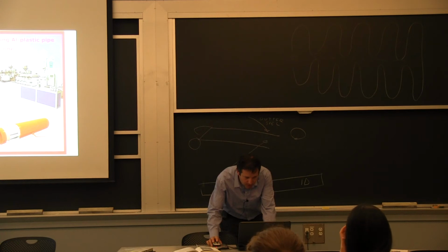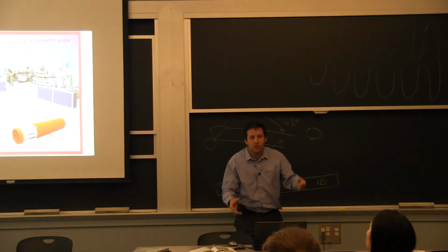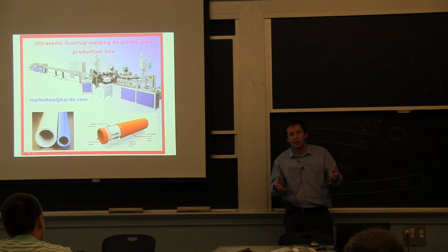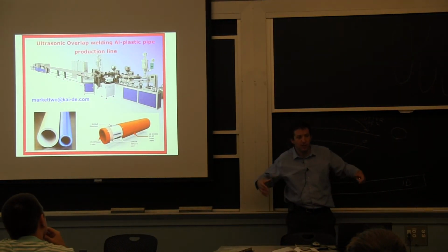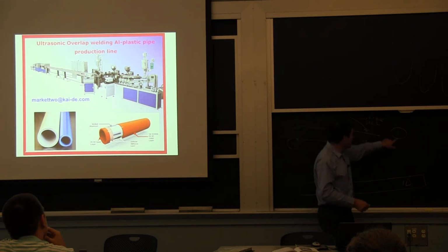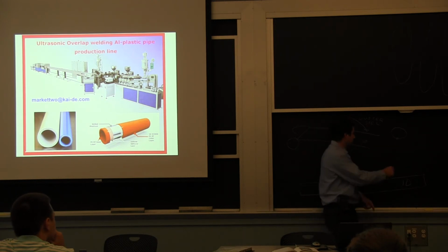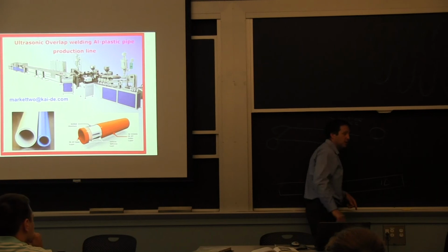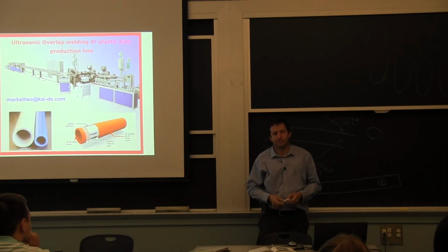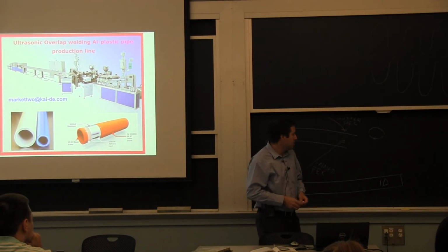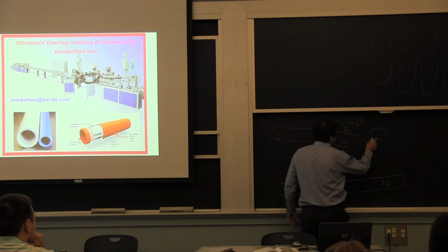If you look at the thickness of the inner layer on one side and on the other, there's no real control over everything here. It's all being put together in the same assembly. And you don't have the same thickness at this lap joint. You have more aluminum, so this is going to affect the thickness of the inner layer and the outer layer.